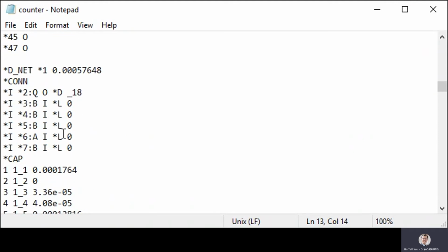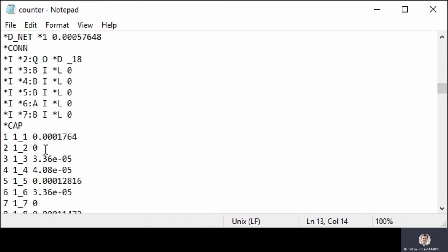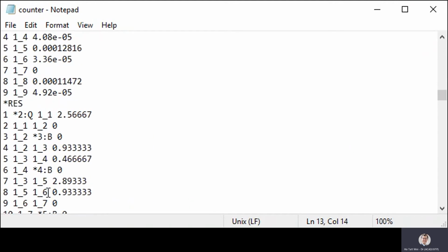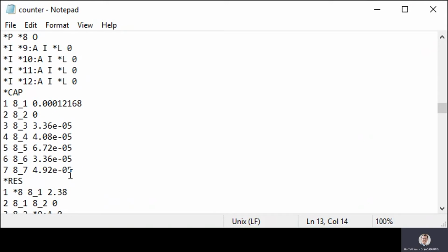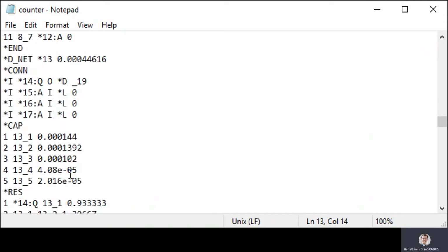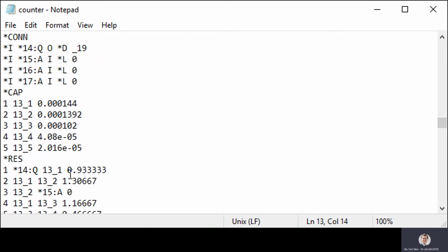So if you go down individual nets, you will see the report of the capacitance values, the report of the resistance values of individual wire connections. And these R and C values, as we'll see in a later part of this course, can be extracted, especially for the critical path, to help you optimize the speed and energy consumption of your design. Okay, moving on.